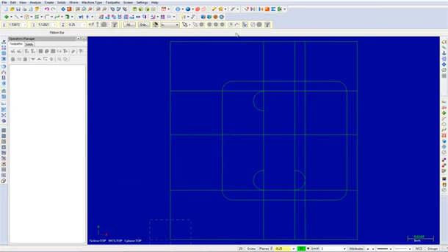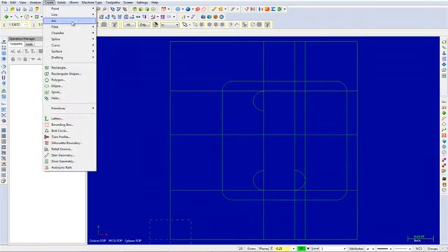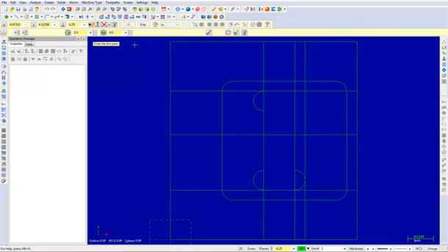The next thing that we will do is create arc endpoints. In this step, you will learn how to create arcs defined by endpoints in a radius or diameter. Select Create, Arc, Arc Endpoints. Enter a radius value of 0.55. Select the following two intersections as shown.